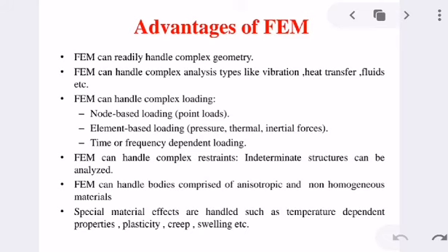Indeterminate structures can be analyzed by using the finite element method, and it can handle bodies comprised of anisotropic and non-homogeneous material. Anisotropic material means materials in which properties such as Young's modulus change with direction along the object, such as composites. And special material effects are handled, such as temperature dependent properties, plasticity, creep, etc.